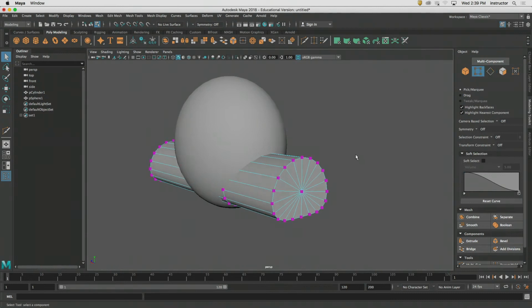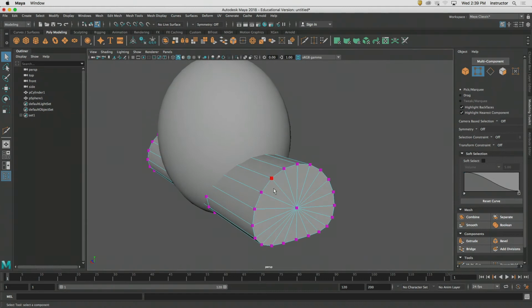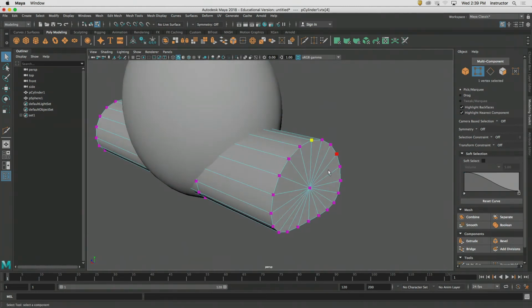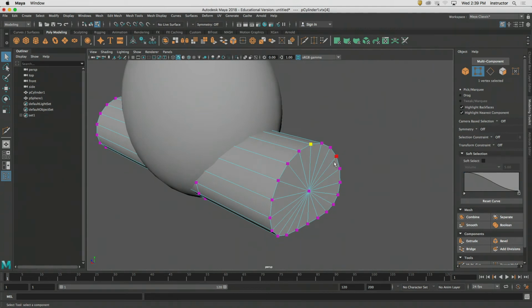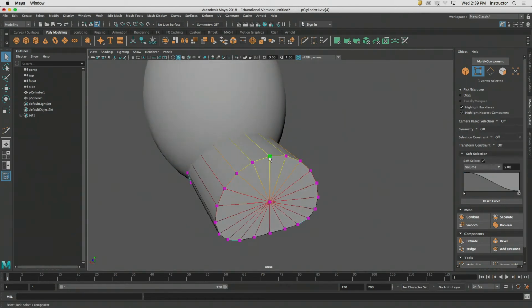Back to the selection tool. And I'm going to go back into my vertex selection mode, and this may or may not give me the result. I didn't have a chance to slice this into quads. But I'm going to select that one vert, okay? The component that we select is going to receive 100% of the influence of the tool, right? So it's like the dead center of the soft selection gradient. Now, the gradient is going to emanate from that point, or whatever is selected, in the center of the selected component, right?